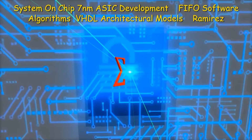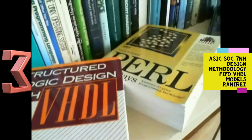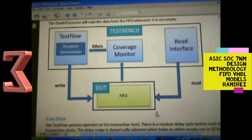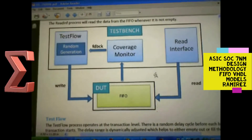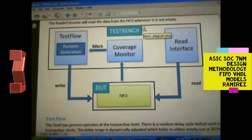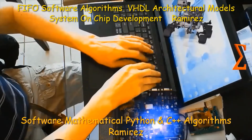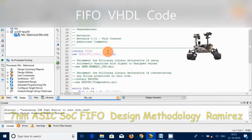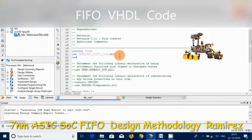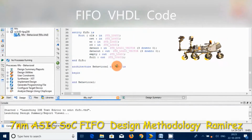So the FIFO presented in this project, as stated by all the facts that I have mentioned, the first in, first out, are essentially memory buffers used to temporarily store data until another process is ready to read it. The first byte written into a FIFO will be the first one to appear on the output. Typically, FIFOs are used when you have two processes that operate at different rates.